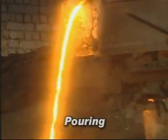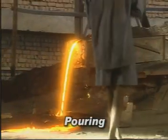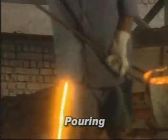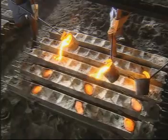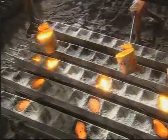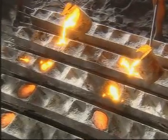For pouring, the molten iron is tapped from the cupola and manually carried with the help of hand ladles. This molten iron is then poured into the individual molds of pipes at 3 points simultaneously.